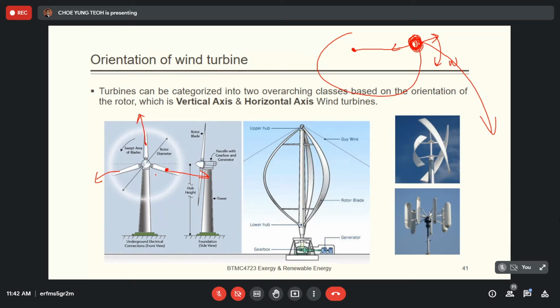So the bending stress and the tensile stress are totally different. The allowable tensile strength and the allowable bending stress are different. If you want to break a ruler, you bend it much more easily than you pull it until it breaks. The same thing happens here. This blade is just pulled by the centrifugal force, so it's quite strong. But this one,